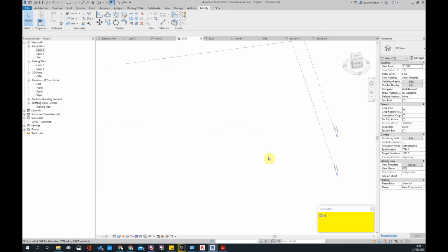Yeah, makes sense. Thanks. So just, because if you measure on the inside of the curve, then you make sure that all of your ramp is acceptable. That's correct. Yeah. So if you use the outside curve, the inside curve would be too steep, in other words.